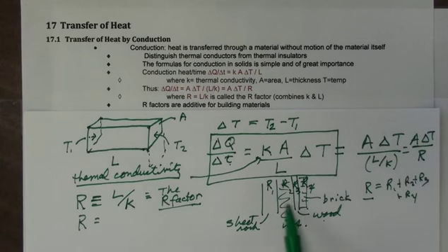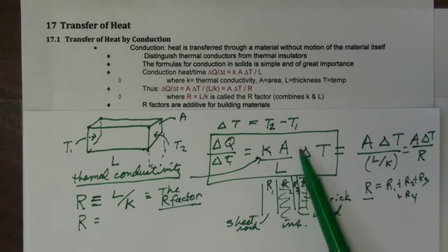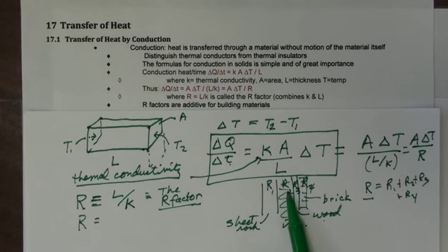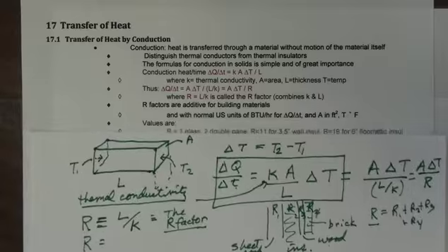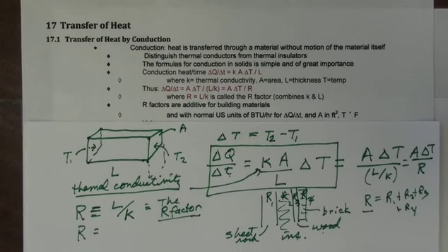And this R factor will apply to the whole system. If, on the other hand, you were to try to use this equation in its original form, you would have to look at the temperature drop across each one of these substances, and the equation becomes extremely difficult to solve that way. So just remember that the R factors are additive. So I only have to worry about the area, the temperature, and what the total R factor is, and it's additive between the substances. Now let me tell you a little bit about R factors.